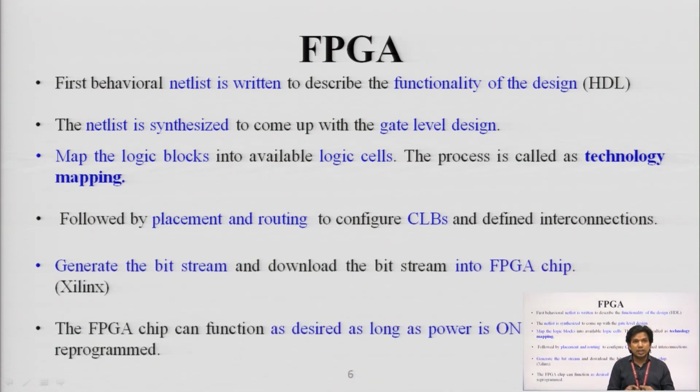Once that is done, our task is to generate a bit stream, so that we can download it into the FPGA by using a tool like Xilinx. Once you have given the input to your FPGA kit, the FPGA chip can function as desired as long as the power is on, unless you reprogram the interconnect.